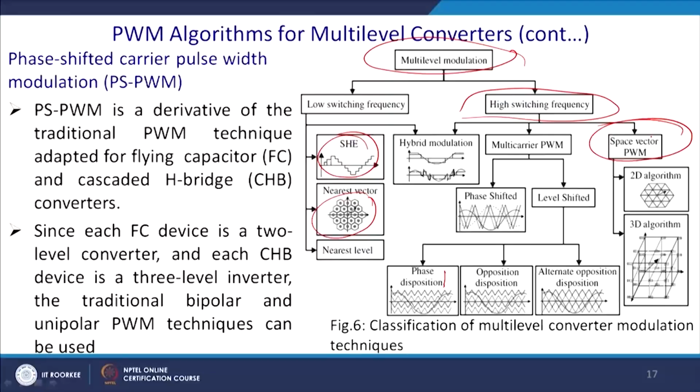Space vector modulation has one advantage: it utilizes the DC voltage better, and for this reason the switching stress is less. Of course, the same can be done by third harmonic injection, but instead you can achieve the same features with space vector modulation.